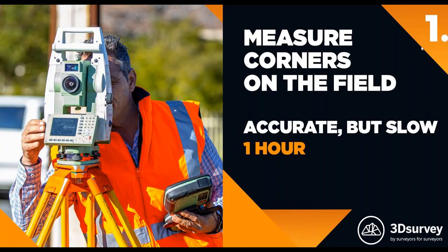So the technique we are using, I'm sure all of you are using right now, is we map them with total station. So either we will use the laser on our total station to measure them, or we will have someone signalize them with our measuring stick and we will measure them. So this method is very accurate, but it's also time consuming because we have to go to each corner and we have to measure it. And the accuracy we can expect for the building corners this way will probably be around 4 centimeters.